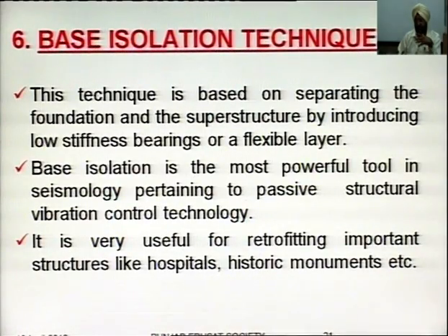Whenever an earthquake comes, the seismic waves, or the earthquake waves, that would transfer from the substructure to the superstructure are borne by that particular bearing and are not transferred to the superstructure. Very simple. In our bikes, in our automobiles, in cars, we have shock absorbers. The basic purpose behind those shock absorbers is to resist the shock, so that the shock may not transfer to the person sitting inside the car. The same is the case with the base isolation technique.